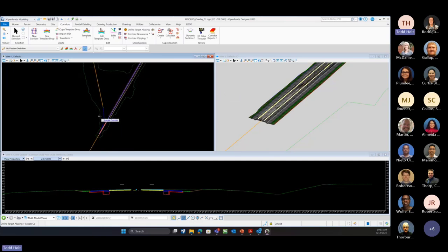On this one, say we have our survey RD file of the existing, but there might be another part of that project or additional survey that's going to come in over here that we want to add into this. We wouldn't necessarily want to go through and create another terrain or add that, but what we can do is create a complex terrain model